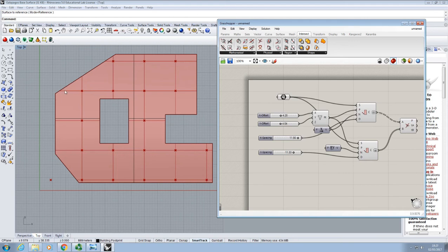So in situations like these, where we've got a very long cantilever coming out the end there, we're going to want to put another column at the end of that grid, wherever it intersects with the edge of this surface, so with the edge of the floor plan. So then these will be our support columns. But we don't necessarily want to do that everywhere. So where we've got very short cantilevers here, it will be kind of a waste of time to put in another column right on the edge there, which was only a few hundred mil away from the column we already had. Because if it's a very short cantilever, then it can probably withstand that without necessarily needing to be deeper than our spanning beam in the middle. So provided it's not going to be driving our structural depth, we're usually okay with having a little bit of a cantilever.